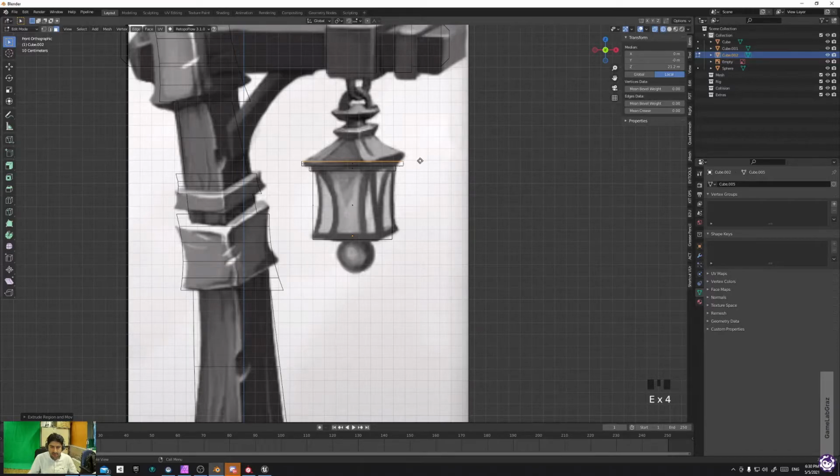In that case, we extrude again and then scale, but it has some curvature, as you see, that we can always add later using that bevel technique that we discussed before. Again, scale, extrude, scale, and extrude only a little bit, scale, extrude, and then extrude and scale.